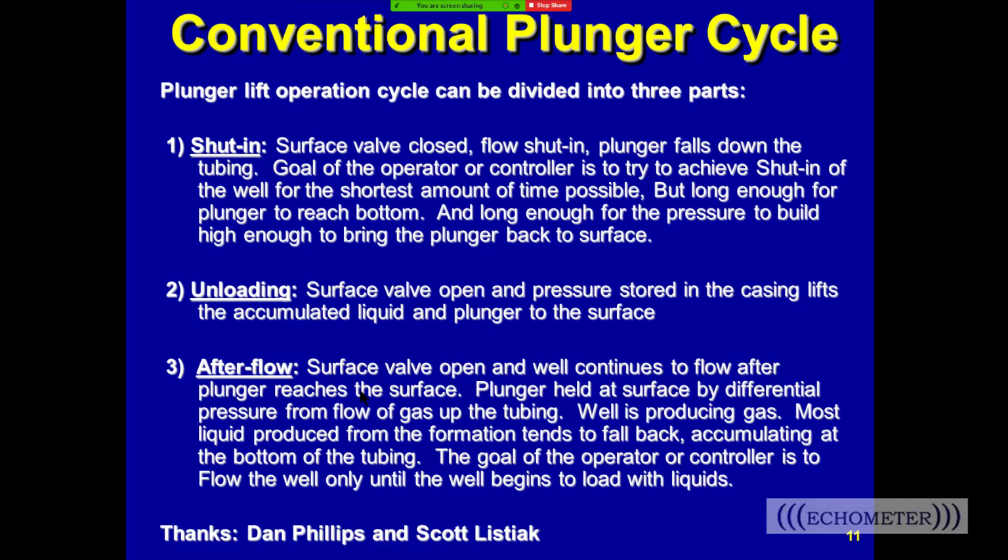Unloading means that some criteria has been met in the controller, time or pressure or whatever the conditions are, and the motor valve opens and the casing pressure starts to drop and the tubing pressure drops, and that stored energy in the casing results in lifting the plunger and accumulated liquid to the surface. Once the plunger arrives, we're in afterflow and we're selling gas down the sales line, and the plunger is typically held at the surface by pressure. And so that's the three parts of a plunger lift cycle.